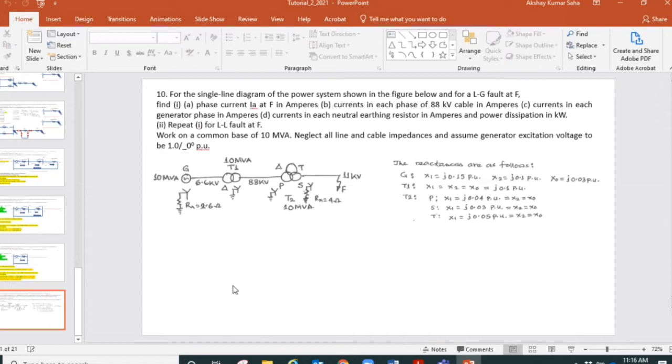So you can imagine one transformer, you have the secondary winding in delta, what is the voltage available at the lines? The other winding is connected in star, what is the voltage available at the lines of that star connection? So that is one thing that you need to make sure. The next thing that you have to make sure is that there is no phase difference.